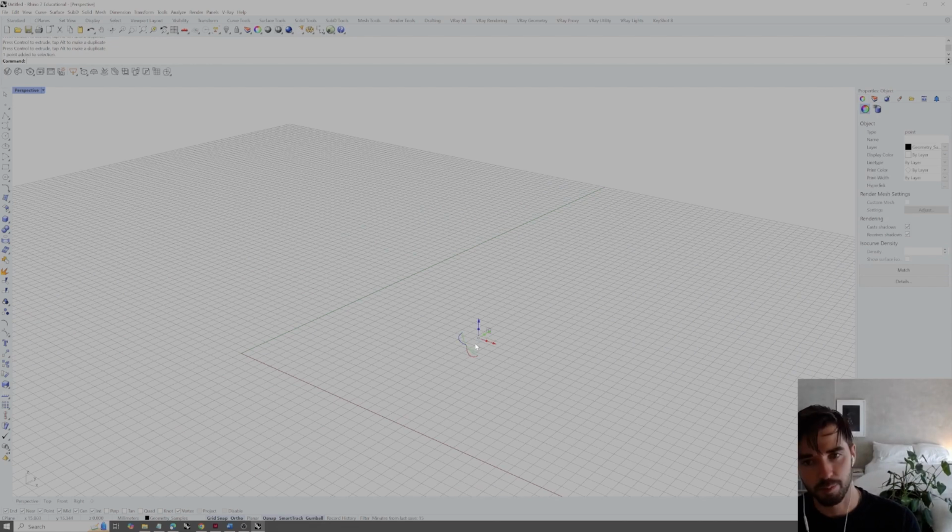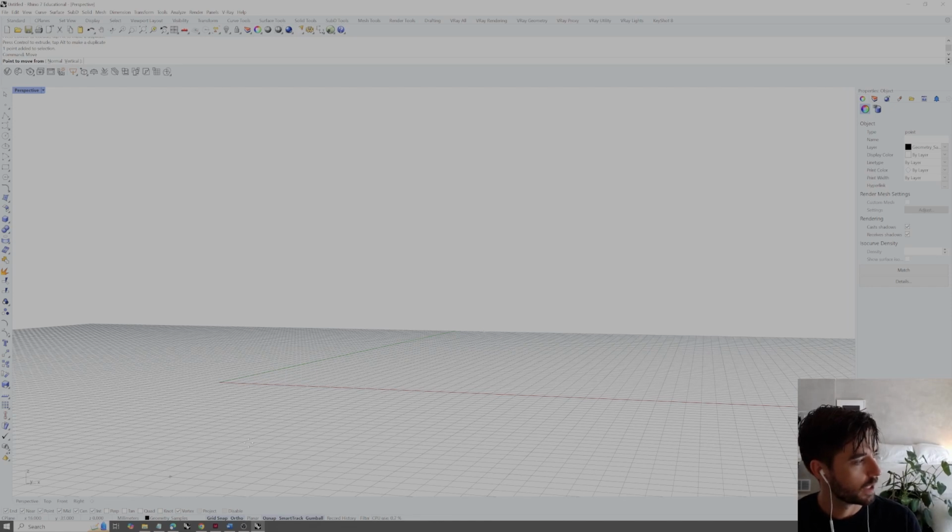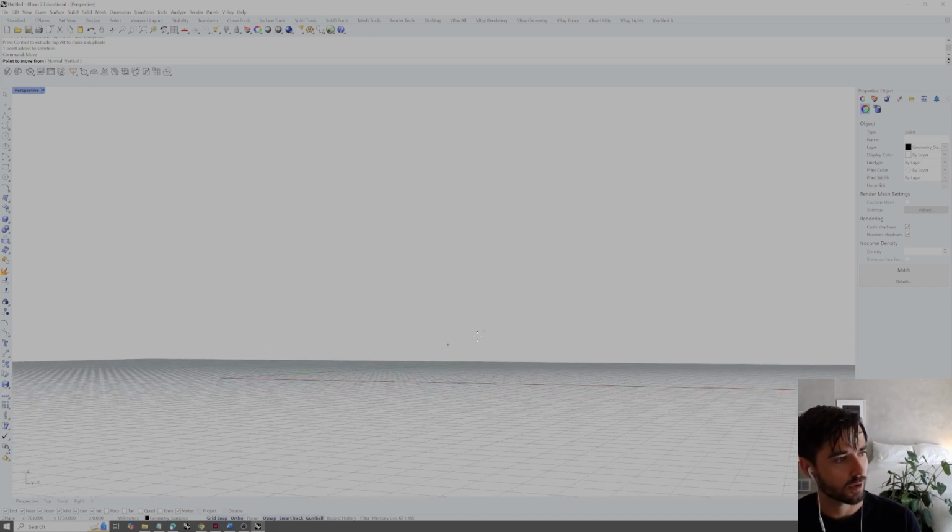If we want to move it straight to the origin, let's say, then we can type a command to move this object, or edit this object, transform this object. And this command is going to be called move. So I'm going to type move, hit enter. It's hard to see, but our point is now highlighted yellow without that gumball. But we can see that my cursor will snap to the point, since my point option down here at the bottom left is checked. This is called our O snap option. So this means our cursor is going to be able to snap to whatever geometry is selected there. So point geometry is selected.